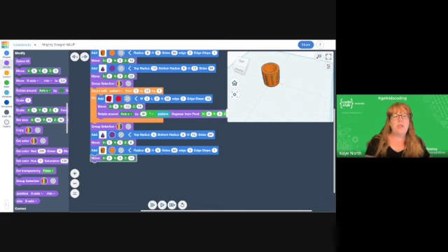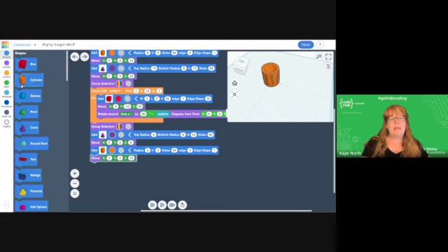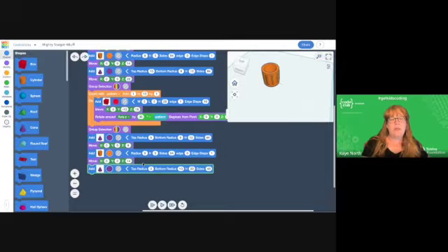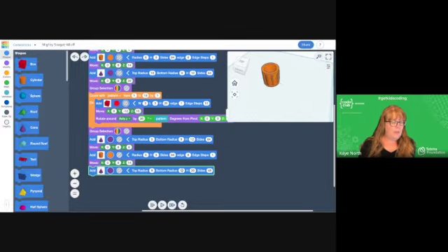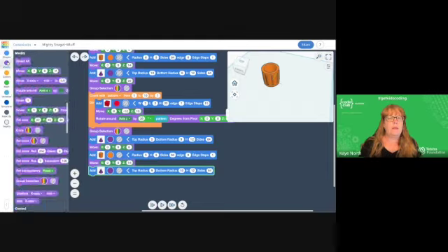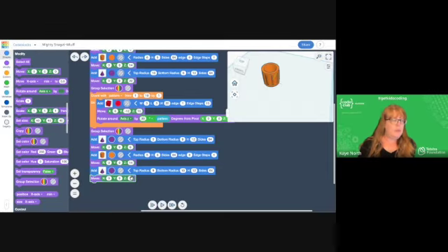The final shape that we're adding in is that inverted cone on the top. It is a solid. So our cone, remember, is the inverse of this one. So the top radius is 9. The bottom radius is 5. The height is 12. And the sides are 64. Just makes a really nice smooth cone. Put in our placement on the Z axis at 22.